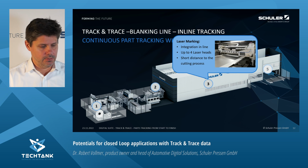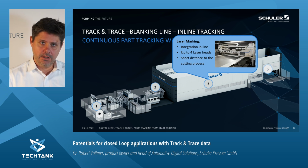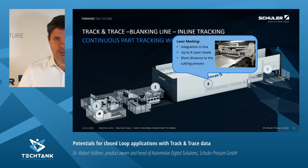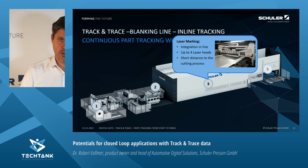That means we do the marking in the processing, as the example here shows, right in the laser cell, for example, or we can integrate up to 4 laser heads from the upper side, but also from the bottom side. We have a really short distance to the cutting process, and this is very essential to have a really precise alignment between the outer contour of your blank and the position of the marking.